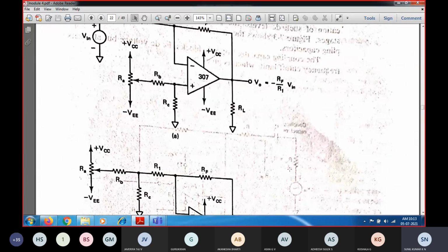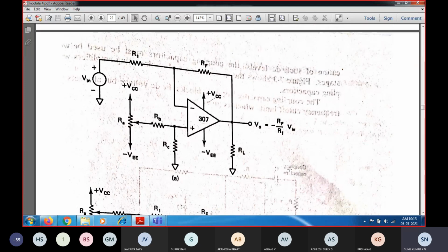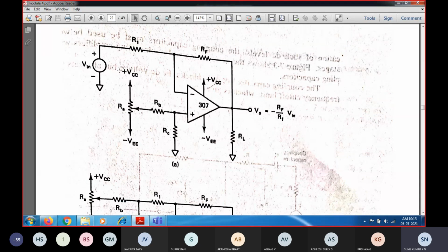Now, coming to another set of amplifiers, operational amplifiers where we are not providing any offset nulling terminals in the IC itself. In order to nullify the offset voltage, what are we going to do? We are going to design an offset voltage compensating network, so that I maintain the offset voltage at nullified, or made equal to 0.